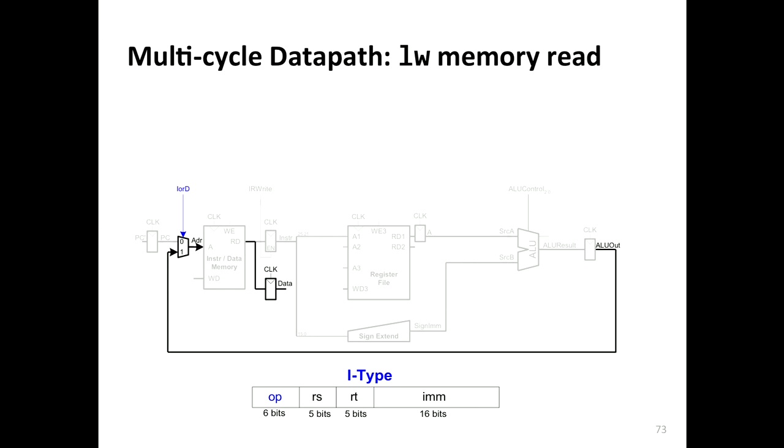And the next stage is you read the memory. You basically need to provide the data path to be able to read, to supply the address that you just generated to the same memory. We're going to reuse the same memory. And then get the data out, and then latch the data. Memory access takes long, so we're going to latch it right away after that. Another register.